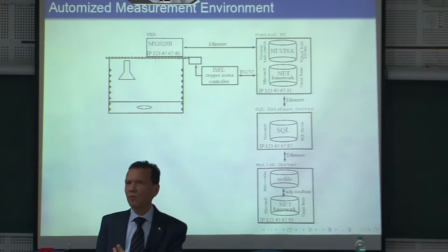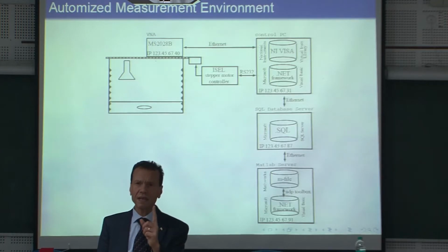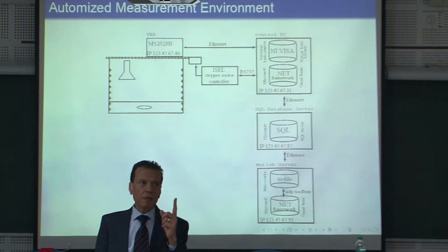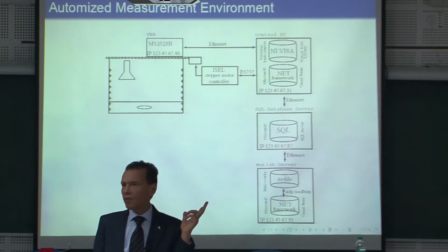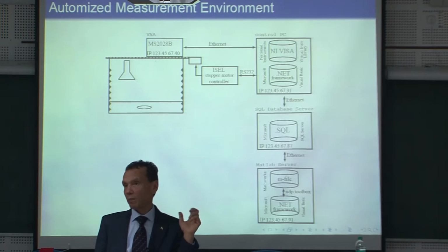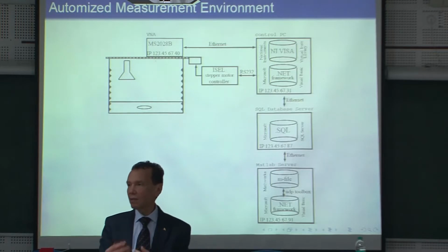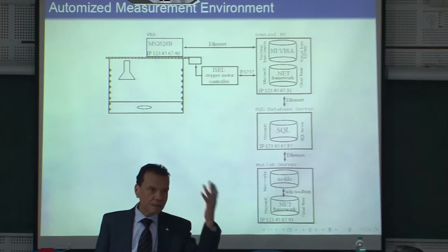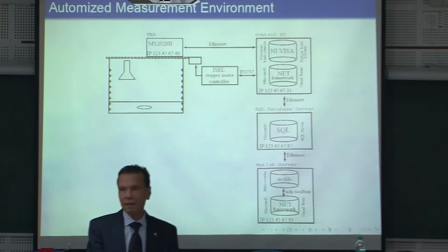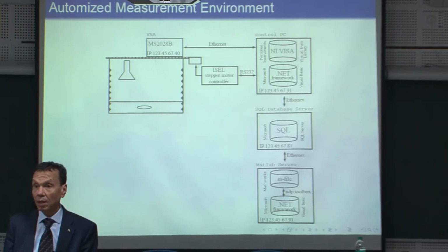At that time, we didn't have digital down conversion. So if you work now around 40 gigahertz and you would like to have the baseband information, you cannot digitize with an 80 giga sample per second sampling rate. Therefore, you must work using analog. So a real mixer. You mix down with, say, 26 or 30 giga in order to bring it around the IF.